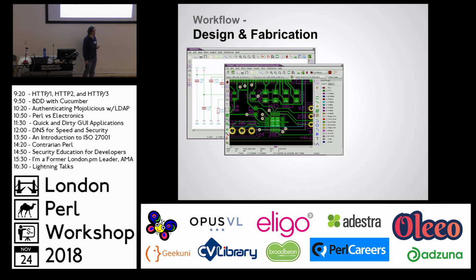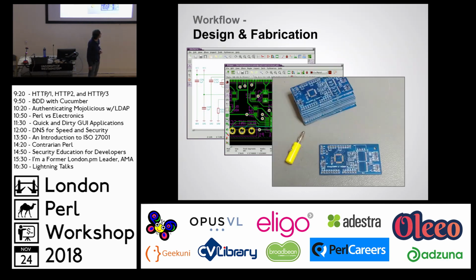And then you send that design off to some kind of commercial company, and they build a board, and then it arrives in the post, and it looks sort of like that with a banana plug for scale. And these things arrive in the post, and then I get to physically build them. So there's lots of ways that you can physically build these. Some people work to a somewhat larger scale of components, where they are largely through-hole sized, and you can do them with a soldering iron kind of on the back of the board, and you just solder each pin individually.